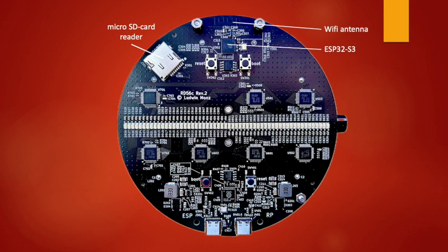In addition to controlling the display, the controller creates the image data to be displayed and sends it via an SPI interface to the second controller, which displays it with the LEDs. The use of an SD memory card makes it possible to store a virtually unlimited amount of image data.